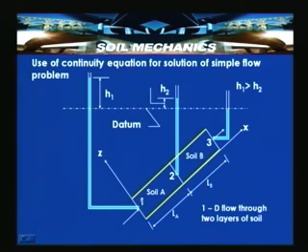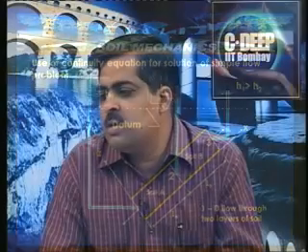The flow is taking place confined between two container walls, along the x direction. So, this is a one-dimensional consideration. Here, at point 1 the total head is H1, and at point 2 the total head is H2, which is to be determined, and head loss has already occurred. The total head which is driving the flow from 1 to 3 is around H1.